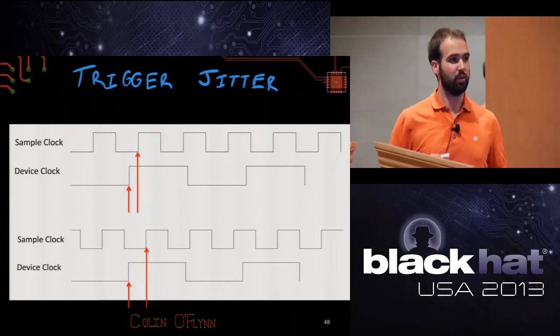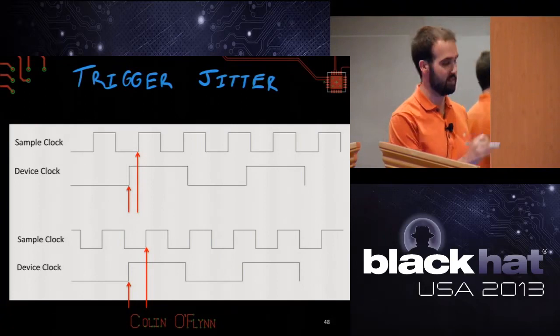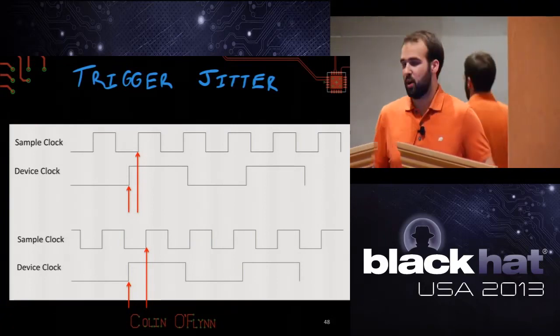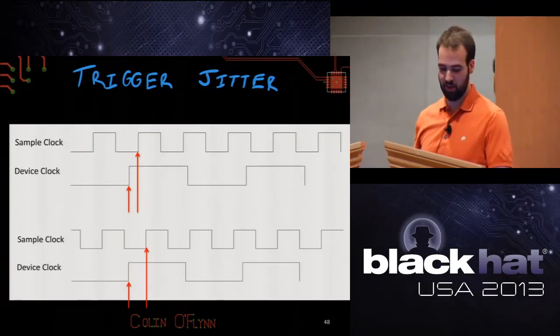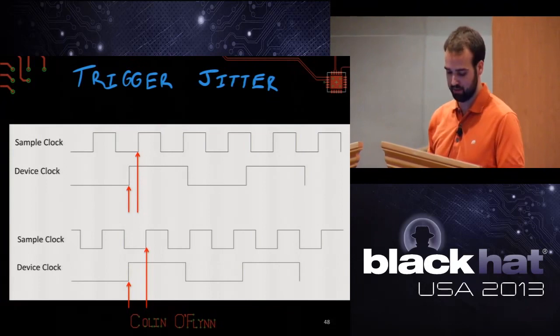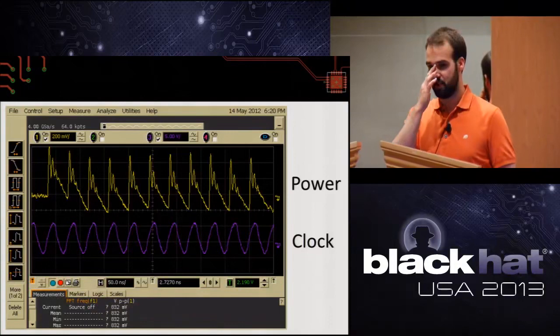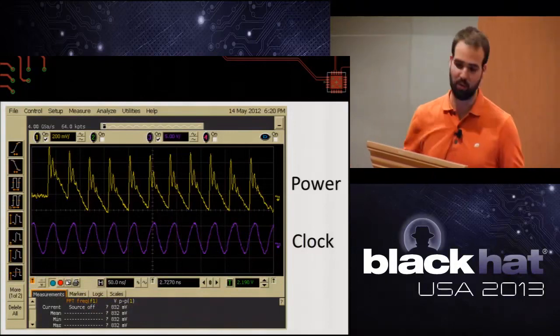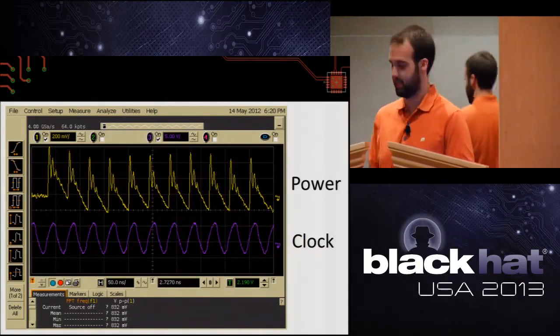If you sample very quickly, obviously, if this sample clock's going up and down very fast, that spacing decreases, this problem's not a big problem anymore. So this is why high sample rates are very convenient, is they reduce this trigger jitter and you get better results. As an alternative, rather than just cranking up the sample rate, you can take a smarter approach, which is to say, well, it's a digital system, I probably have a clock. I can just use the clock and sample on the clock.